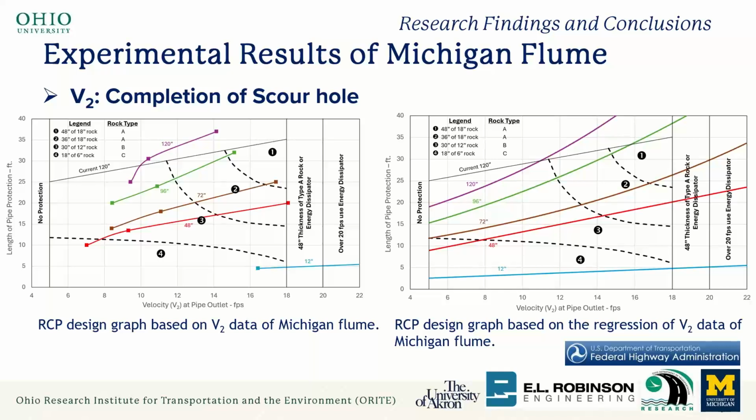So parameterizing the required RCP length as a function of culvert outlet speed, without taking into account whether that outlet speed is subcritical or supercritical, appears to be missing something. Whereas if we parameterized it as flow rate, that would give a more universally applicable answer. And if that's not clear, happy to discuss that more.